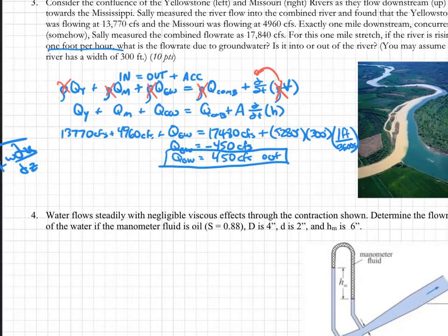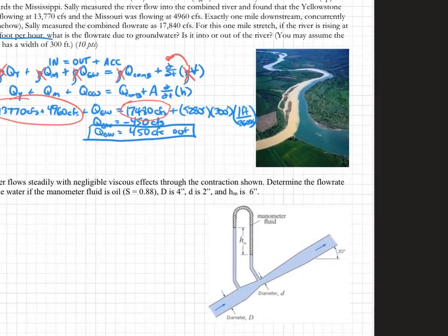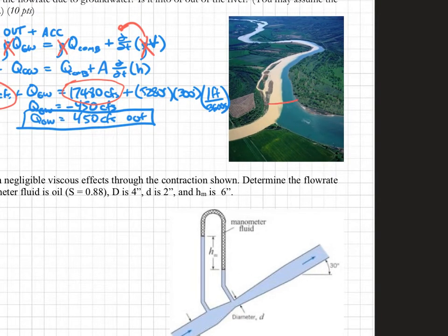Okay, so first thing I want to note is that more water is coming into the system via river flow than is leaving. Okay, so we've got a big arrow here and a smaller arrow here. Okay, so that implies that there was a flood or rain upriver. Okay, and that flood is moving downstream.